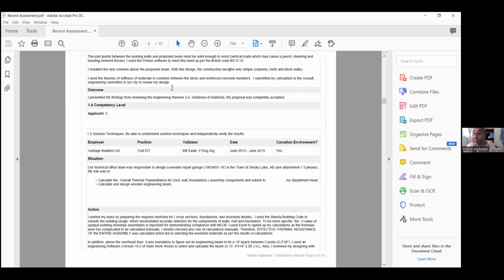It may be in the high range in Alberta, and that may lead to cancer. And for most buildings, you have to think about the area of the building. So you can add a sump bed underneath the slab on grade, and you have pipe and vent, to protect your building from this toxic gas that can lead to cancer. This is one kind of solution.